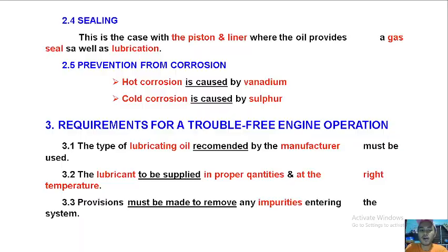If it's too hot, the lubrication properties will be too thin to protect against metal to metal contact or abrasion. Provisions must be made to remove any impurities entering the system. So we do have a filter, and if possible, clean the filter at all times or if necessary.